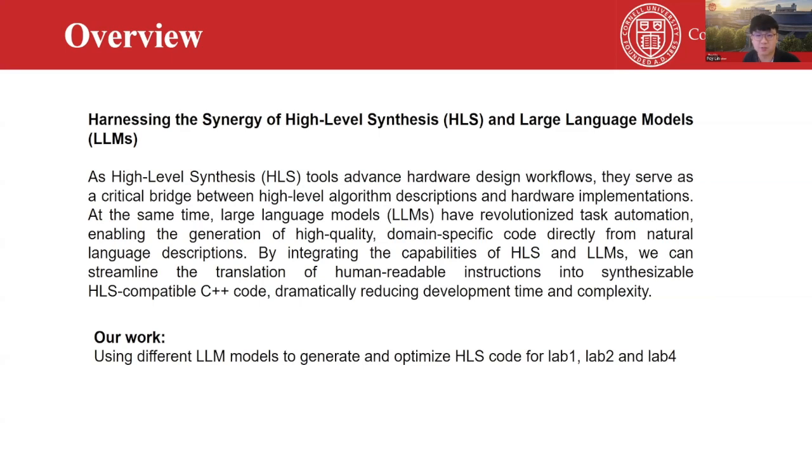And one thing to mention is why we are translating the natural language into C++ code, not Verilog. This is because the LLM is more capable of dealing with C++ code than a hardware description language like Verilog. So if we translate the natural language into C++ code first, and then use the HLS tool to translate it into Verilog, the accuracy is actually higher than just using the LLM to translate the natural language into Verilog, by 10%. So that's why we are doing this.